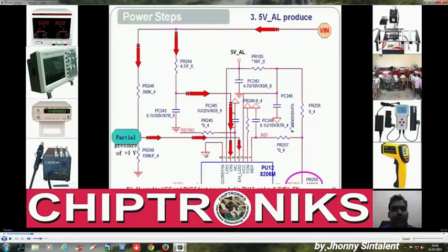The first step is V-in coming at pin number 6, and another thing is required, that is this V-in through a resistance divider is going to enable LDO. This is the second step. You can check V-in is going over here, it's enabling the IC, it's giving the supply voltage to the IC, and the V-in with a resistance divider, that is 4 volt. Here this resistance divider divides the voltage, and 4 volt is fed to enable LDO, that will enable the internal linear regulator, and LDO means low drop out.